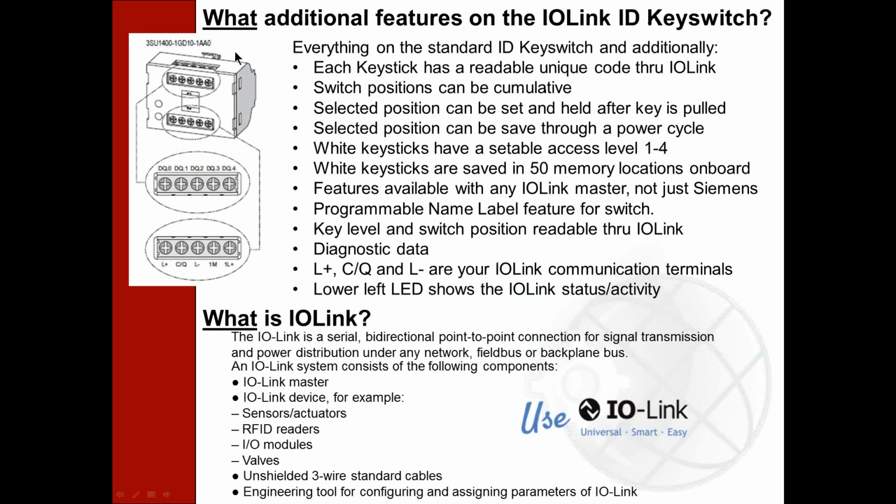So this goes into what the additional features are on the IO Link ID key switch. Again, I would highly recommend going with the IO Link ID key switch, even if you're going to use this as a standalone unit. And as a standalone unit, you could wire these outputs into your PLC to supplement your logic. I'm sure everybody understands what I'm talking about there.